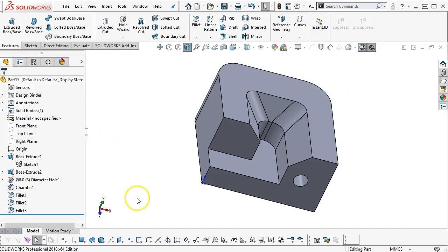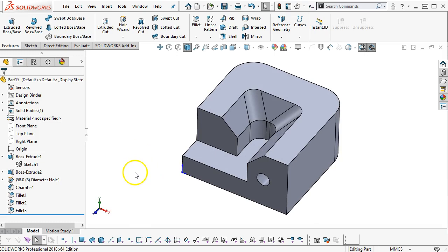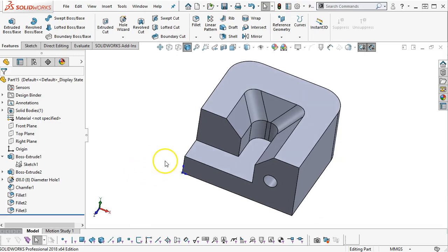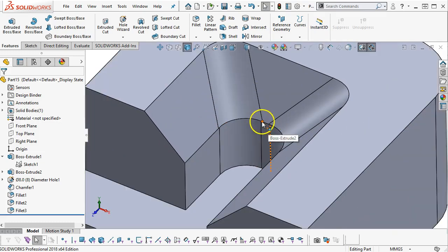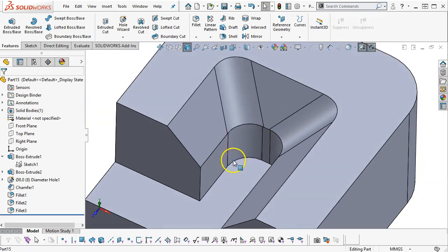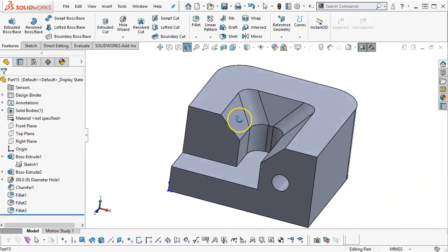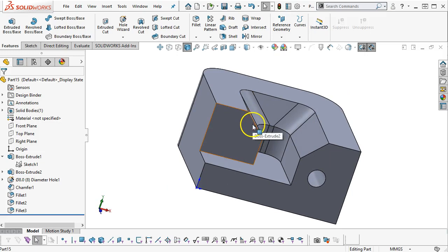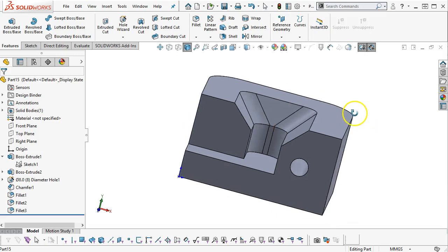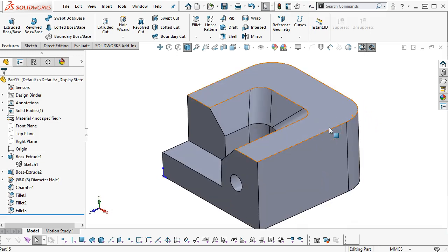All right, but I pretty drastically changed the part, so I'm really going to have to check the functionality and the fit. As far as the blend, you know, maybe a little more on the radius, and the blend cleans up quite a bit. But I made kind of an assumption there that the round tool is now going to be narrower at the bottom and tighter at the top. So even that's not a really good representation of the cut.